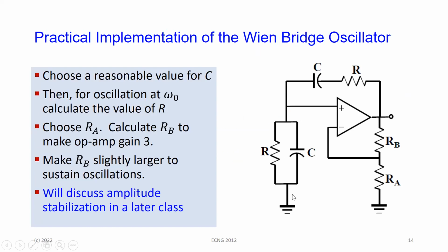It's fairly simple if you think about what you're trying to do. One, you're trying to find a frequency of oscillation. That is where this network comes in. Having found a frequency of oscillation, you then determine what is the gain at the frequency of oscillation. And then whatever that gain is, you have to multiply that by something to make the overall gain 1.